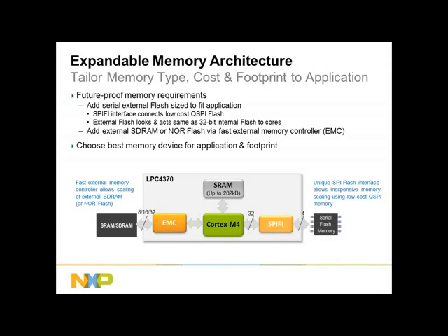If you're familiar with CoreMark, you can go to coremark.org. It used to be, and still is, I guess, a great way of comparing microcontroller cores. So if you want to know the difference between an ARM core and a Renesas core or a Microchip core, you can go to CoreMark and see some relative benchmarks. Now, if you're comparing a Cortex-M4 to a Cortex-M4 core, then essentially it's going to be identical, but what you're really comparing at that point is the efficiency of the C compiler being used.